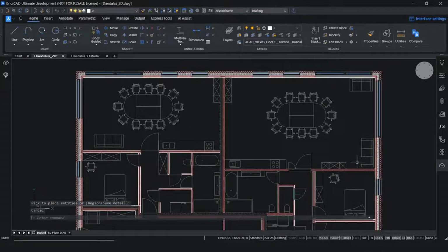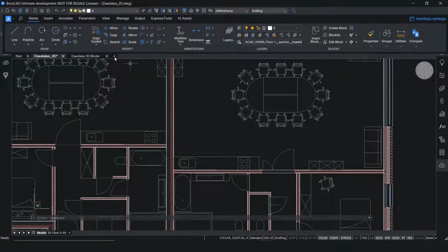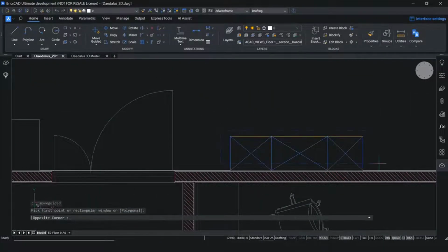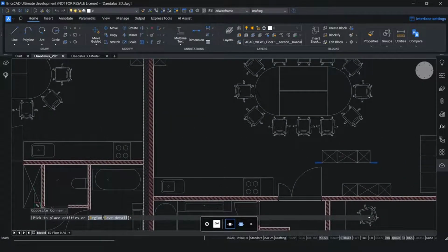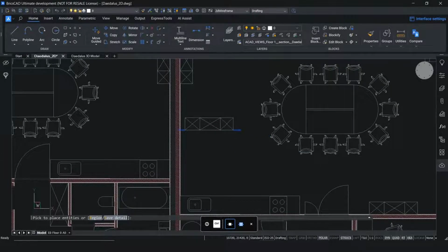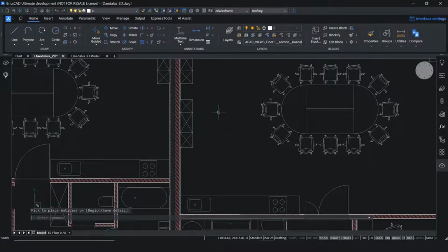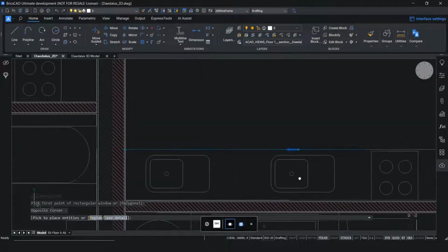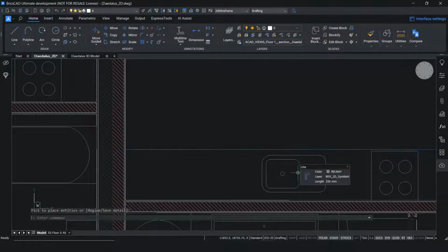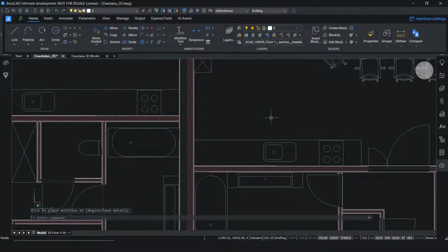Similarly, we can use MoveGuided to move objects in the same guided way. So let's launch it. For example, maybe we want to move these cabinets here from one side of the room to the other. Let's select it, and again, these 2 blue arrows indicate how the cabinet will snap. It's just that. Or hey, maybe here the sink in the kitchen area. We want it to be more centrally placed in the kitchen. Again, by selecting them and snapping to the desired location, we can even use the dynamic dimensions. We can easily place this sink in the place we want.